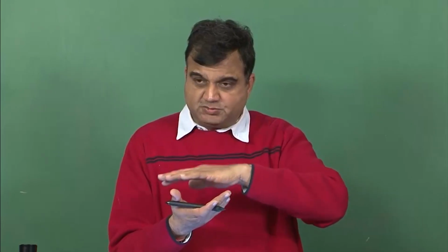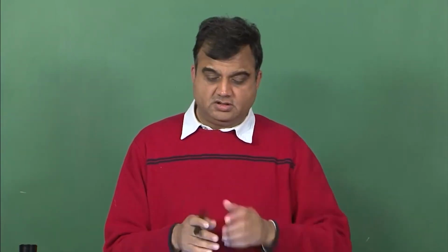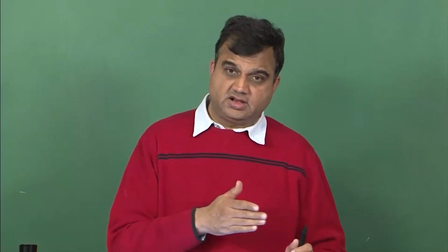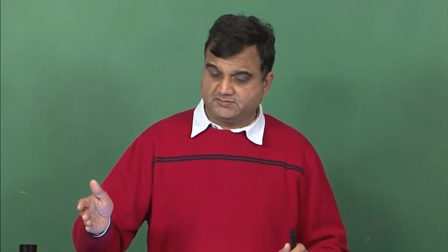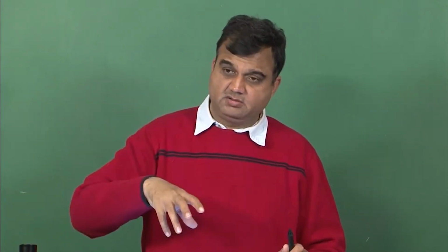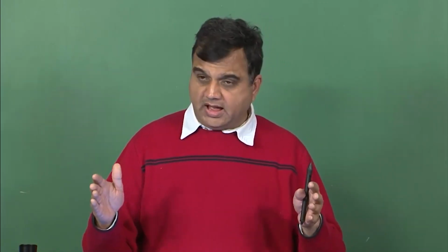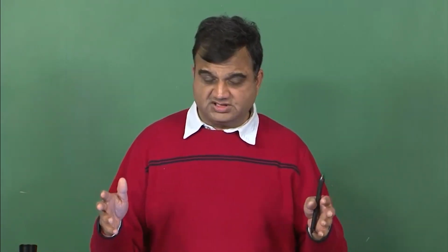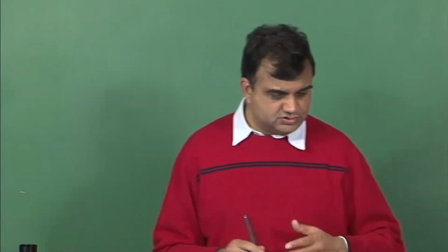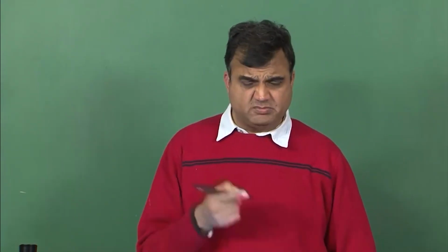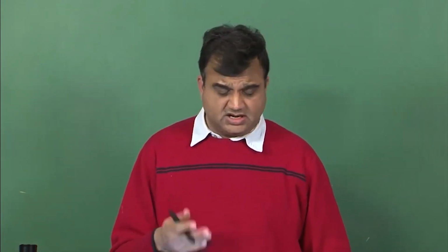Because of heat the curing reaction is faster, and because of pressure attributable to vacuum, you have higher density and more consistent material. So this is what this bag molding process is about, and we will see some pictures to understand this in a better way.